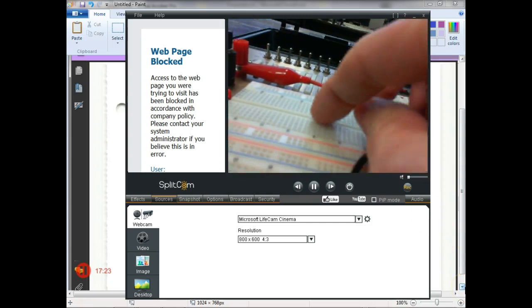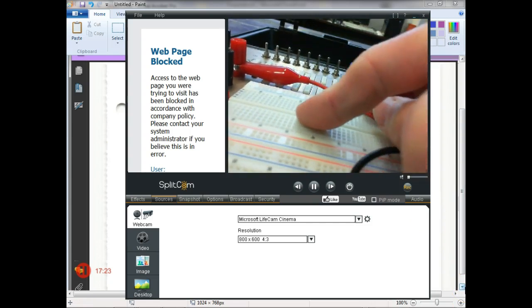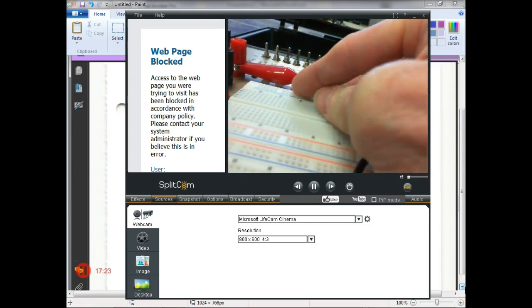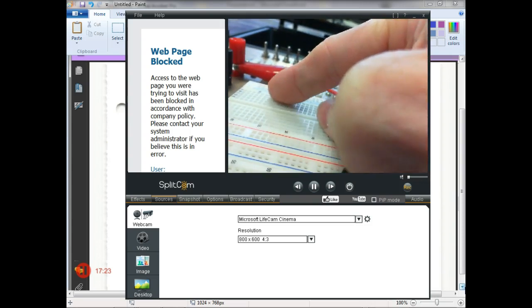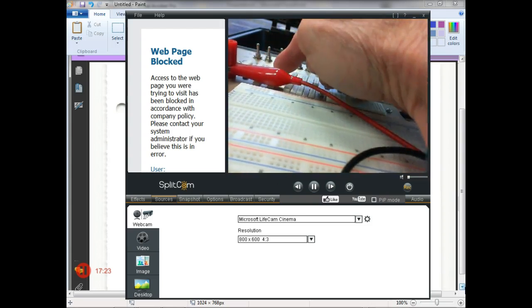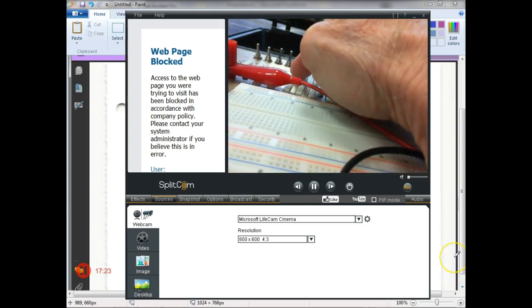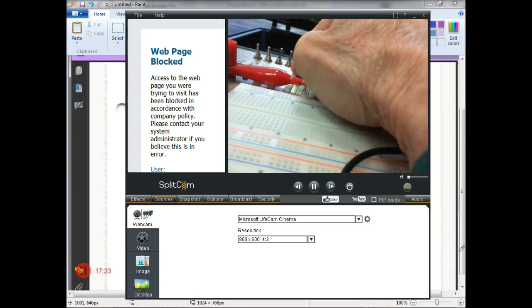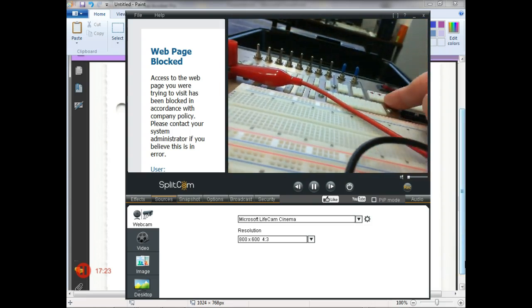So we're going to wire it across the trough, right? You understand that, right? And then we're going to bring plus 5 volts in ground and common up to here, right? You understand that. Then we're going to take the inputs and wire them up to what? 2 of these data switches. Which ones? Yeah, any one, right? And we're going to take the output and wire it up to one of these LEDs.